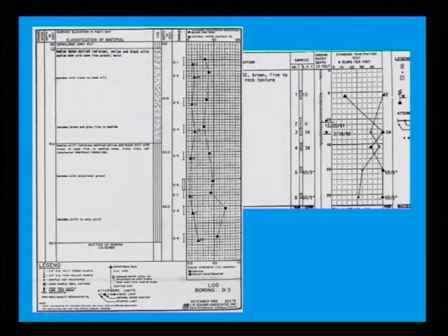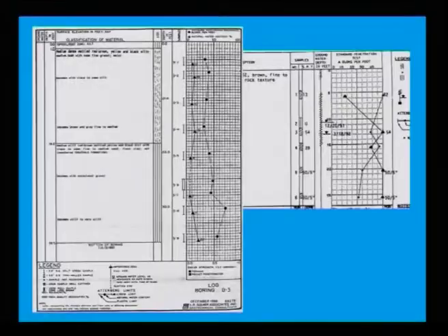classification of soil. As per your testing from laboratory and field, you can classify it. Then samples, at what depth you collect the undisturbed sample. If you look here, I also explain that at this depth, this undisturbed sample has been collected.